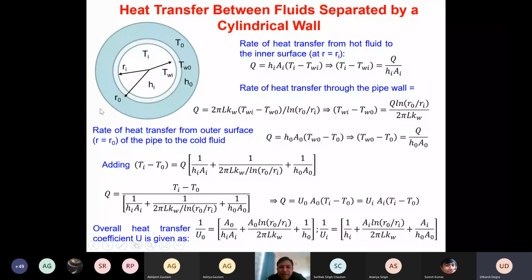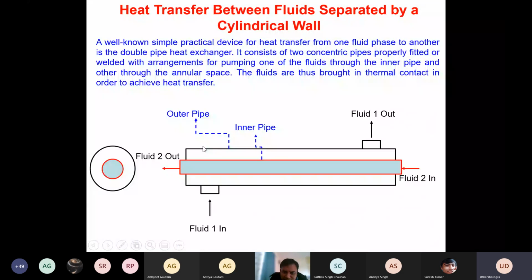Remember, the heat transfer is taking place over this surface or the length, isn't it? It's not only at this instant at R. This is over the pipe, isn't it? If I go back here, this will be the inside surface area, this entire thing. So what will be this circumferential area? Pi d l, isn't it? Similarly, outside surface area is pi d naught l. Inside surface area will be pi di l. Outside surface area will be pi d naught l, isn't it?